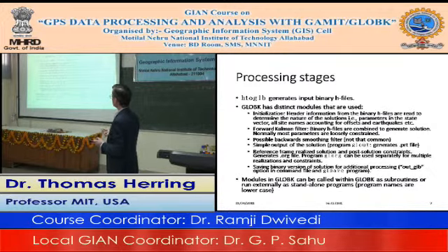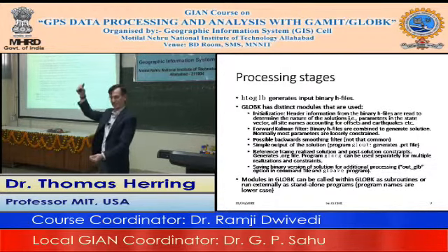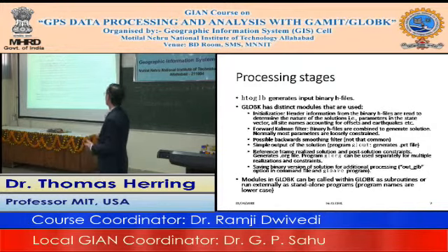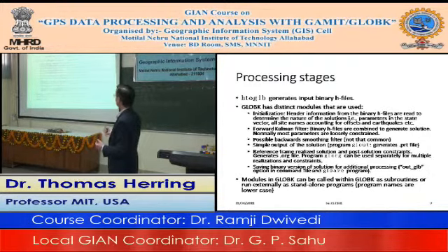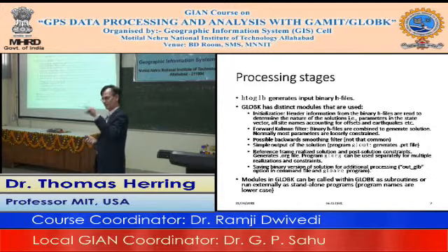So GLOBK itself, when it runs, has several unique steps that it goes through. There is an initialization step, and in that step, all the headers of these binary H files are read to determine the nature of the solution that is being given to it. That's the parameters being included in what's called the state vector in the Kalman filter. It's simply the things you are estimating. It works out all the different site names that are there, accounting for all the different offsets and earthquakes. So there's a set of information in the GLOBK command files you have to give it first so that it can do this calculation correctly.